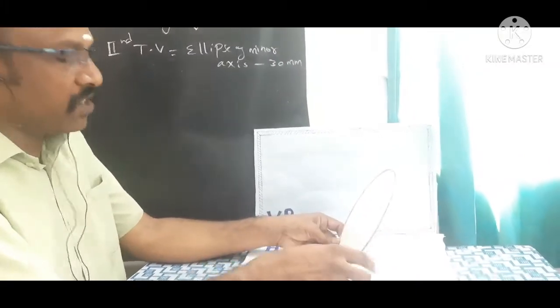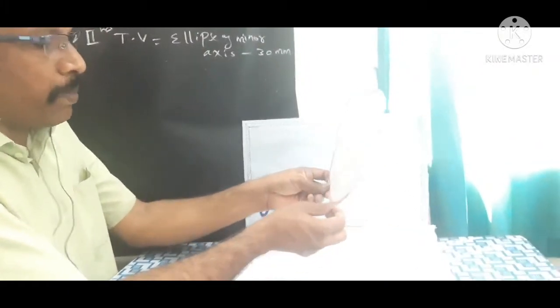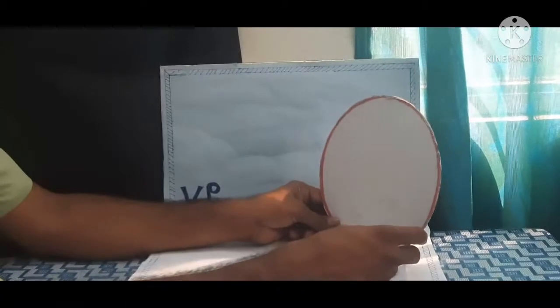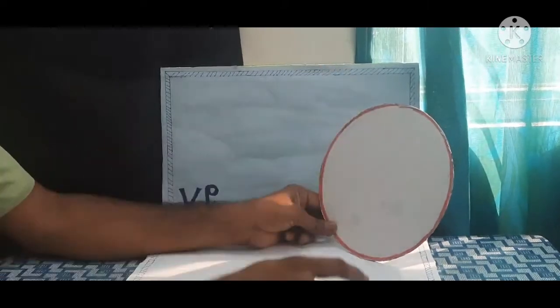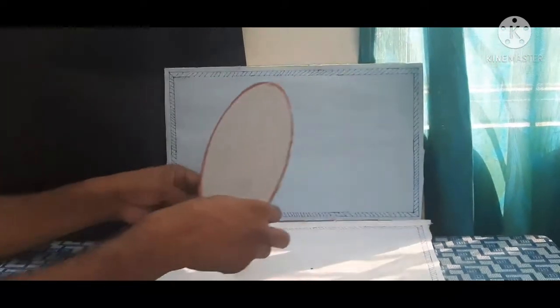Finally, for stage 3, we need this point. The resting point A, we need to tilt for 30 degree inclination with VP. Like that way we can tilt. Then you need to draw the corresponding top view and final front view. This is for demonstration purpose.